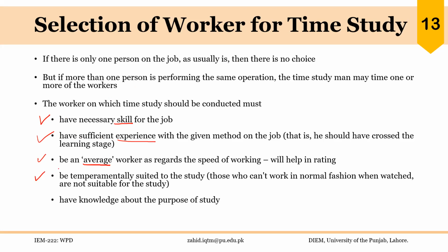Be temperamentally suited to the study. So he should not get confused while being observed, because that is a big problem in stopwatch time study. And the worker being observed should have knowledge about the purpose of the study. So the worker should not have fear that after the time study, our piece rates will reduce. So you have to take the worker into confidence before performing the study.